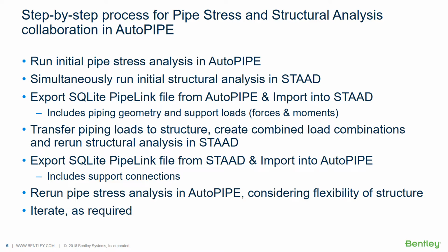On the Pipestress side, unfortunately, a lot of times we just stop here. Pipestress engineers run that initial Pipestress analysis and say, okay, it's passing all of my requirements and criteria, so I think I'm good to go. That is not the best approach. The best approach is to take into account your realistic model, which means considering what your piping is going to be connected to, which a lot of the time is a structural model. We'll look into this a little bit further, but I just want to mention that after those first two bullet points, a lot of times we stop, and that's not necessarily good enough.